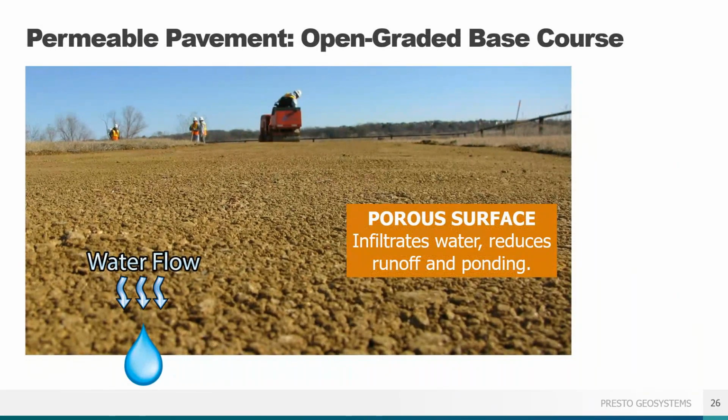One important advantage for any unpaved surface utilizing GeoWeb stabilization is the use of open graded base course. Since we do not need fines to achieve compaction for base stability, the system will function like an on-site detention basin, storing water in the void space of the GeoWeb infill.